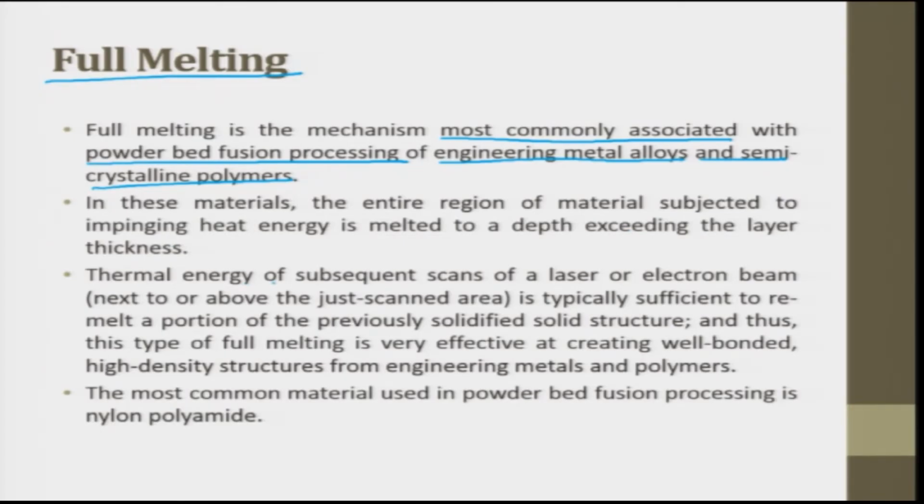The thermal energy of a subsequent scan of the laser or electron beam is typically sufficient to remelt a portion of the previously solidified structure, and thus this type of full melting is very effective at creating well bonded, high density structures for engineering metals and polymers.